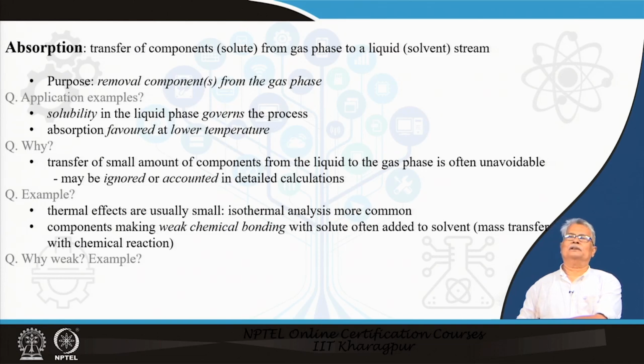In case of gas solubility, the solubility decreases if the temperature goes up, and since solubility is a major controlling parameter for absorption, the lower the temperature, the better will be the carrying capacity of your solvent, or rather the liquid phase.